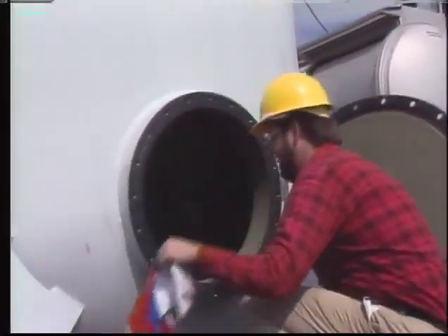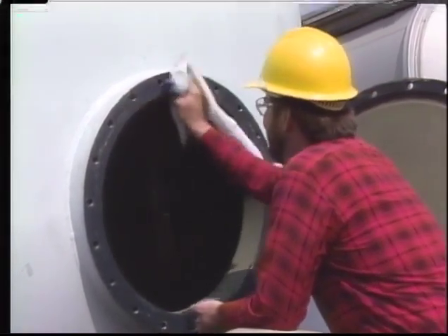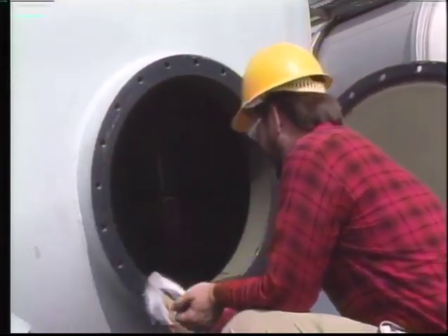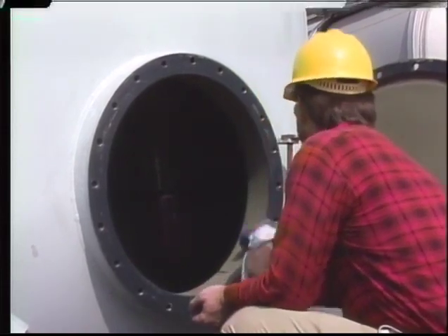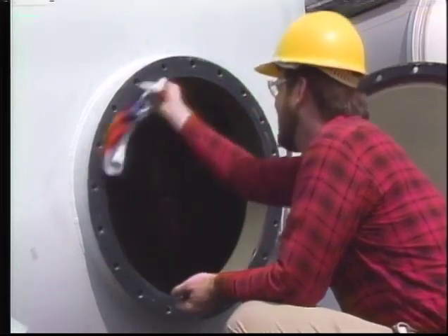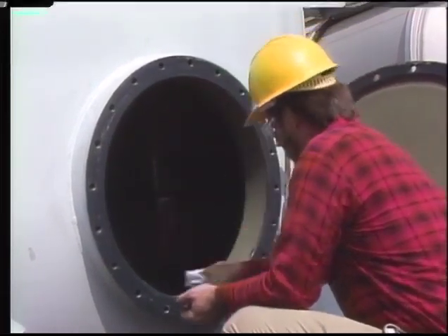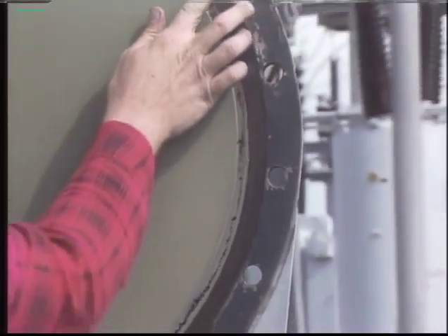The interior of a breaker is cleaned for a number of reasons. One reason, with an oil breaker for example, is to reduce the amount of oil or residue that you get on yourself as you work on the breaker. Another reason is to remove carbon, arcing residue, or moisture that may affect the ability of the breaker to extinguish an arc. As you clean the breaker, you can also inspect it.